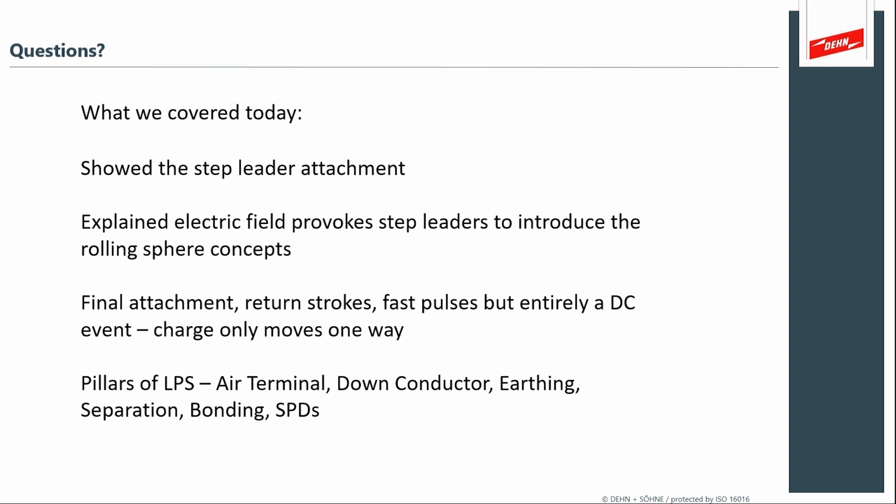Mark, I'd just like to make the comment with this one. There's a couple of factors that are dependent on the class of lightning protection level according to the standards. The first thing is basically the rolling sphere. If you employ this method where you can calculate the sag that the rolling sphere would be, it would also guide you towards the radius of the rolling sphere used. So from there you can then see what lightning protection level was used.